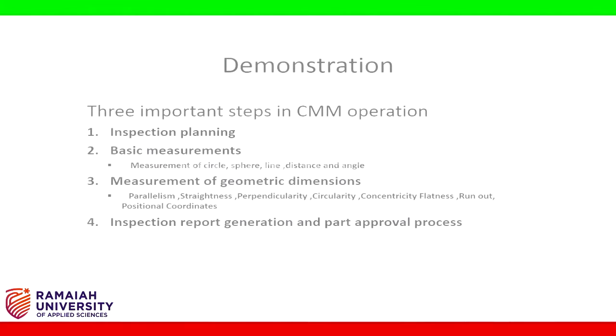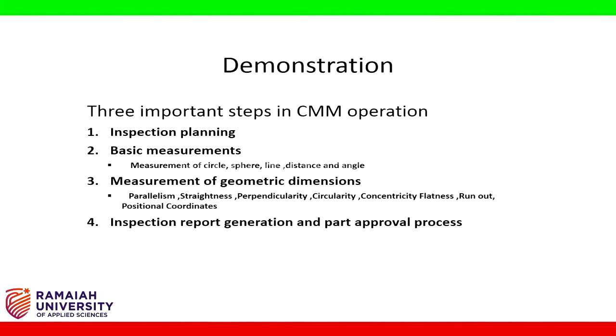Four important steps in CMM operation. 1. Inspection planning. 2. Basic measurements. 3. Measurement of geometric dimensions. 4. Inspection report generation and part approval process.